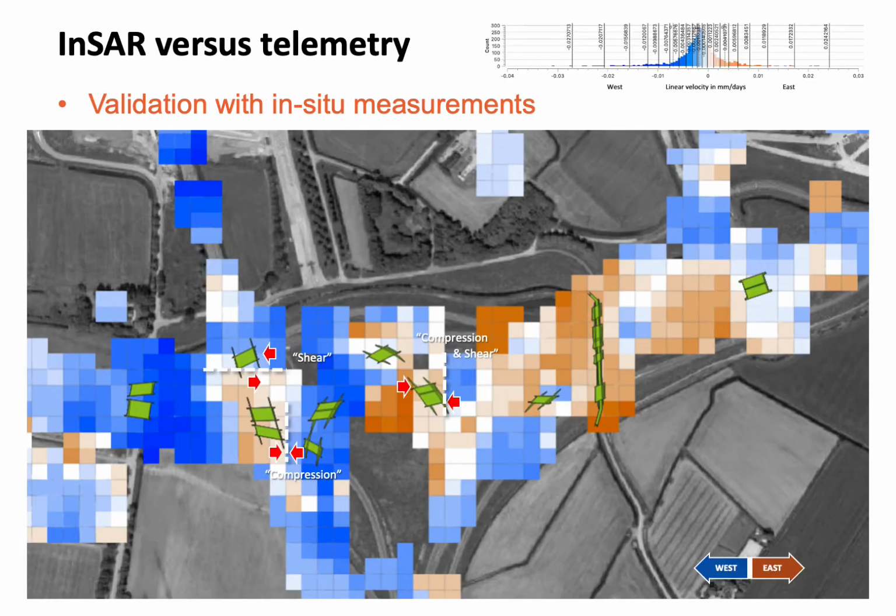You see here a map of the linear velocity of the horizontal displacement after line-of-sight decomposition. We aim to demonstrate that it is possible to accurately represent the important role the horizontal component of the deformation has in the interpretation of the stress inflicted to infrastructure. We can identify areas of shear, extensive, and compressional deformation.